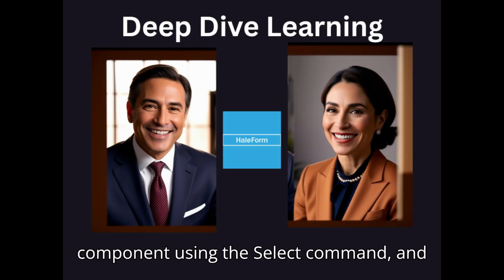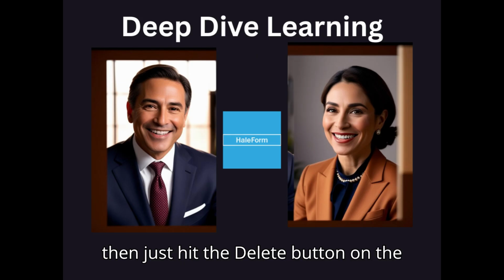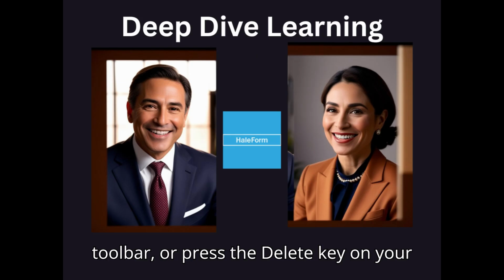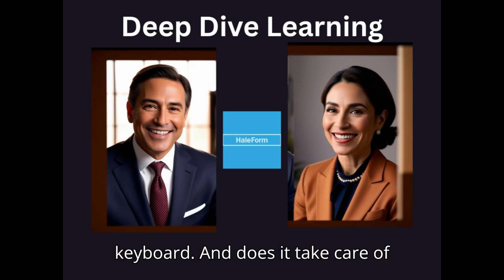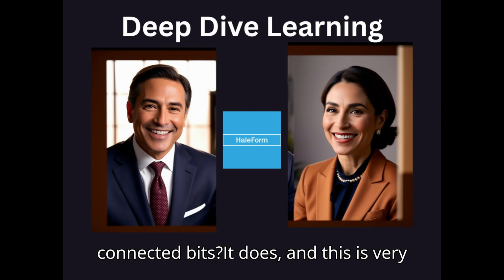Dead simple. Select the component using the Select command, and then just hit the Delete button on the toolbar, or press the Delete key on your keyboard. And does it take care of connected bits? It does, and this is very helpful.